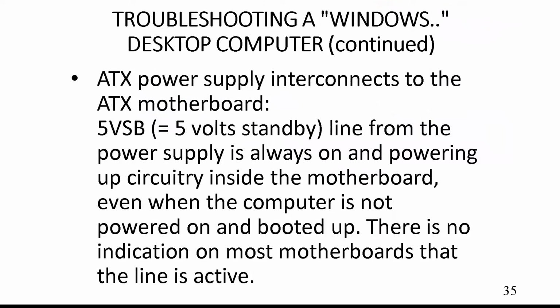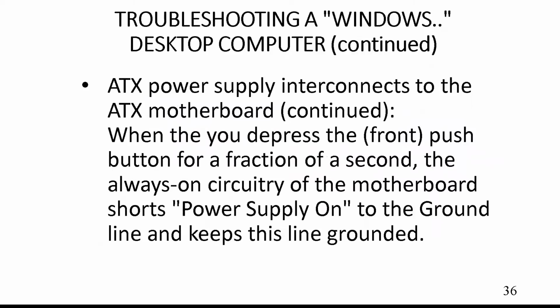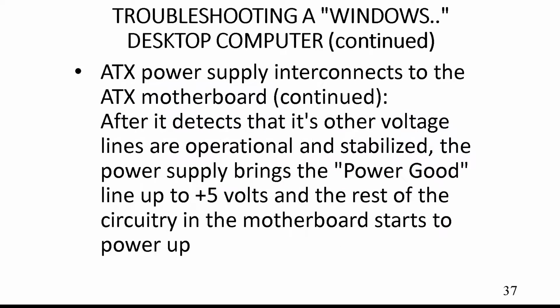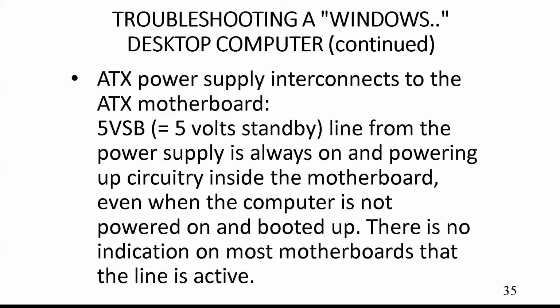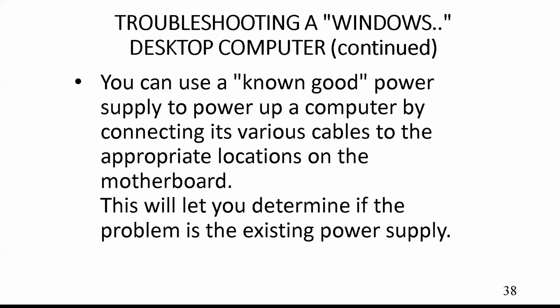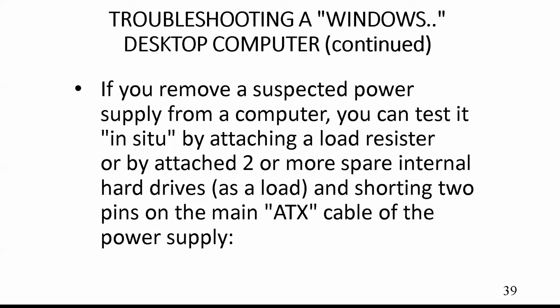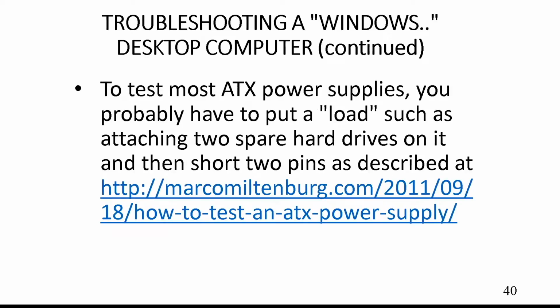There's actually 2 ways to test them. Let me show you. One way is just swap out the power supply with another one, right? And if it works, your computer starts working, then you have a bad power supply. The other way is, I'm going to jump through this fast because I think that it's a little redundant. You can't test these power supplies, 90% of power supplies, without putting a load on them. But adding 2 spare hard drives on them is considered a good load. I don't know why they want 2, but that's what all the techs do.